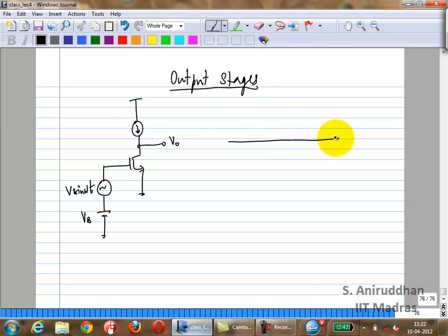Now you can think of three cases relative to the value. So what are the parameters we are interested in? So of course VB is a parameter of interest, V is a parameter of interest, and of course the threshold voltage is a parameter of interest because it decides when the transistor turns on. These are the three voltages in the circuit which are of interest. Okay, output voltage will just be something times V. So we don't worry about that now.